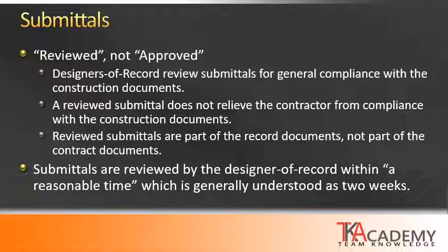A review of a submittal does not relieve the contractor from compliance with the construction documents. The reason for this is submittals are not part of the construction contract. The construction contract is what the general contractor is being held to comply with. So the term "approved submittal" would designate some type of action on behalf of the architect that it meets the contract, and that's not part of the role here. Again, submittals are not part of the construction contract. Submittals, however, do become part of the final project record documents.